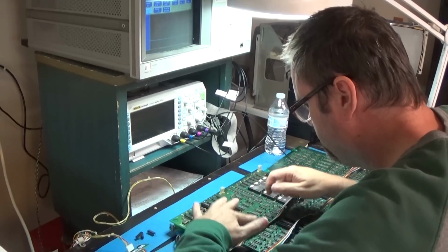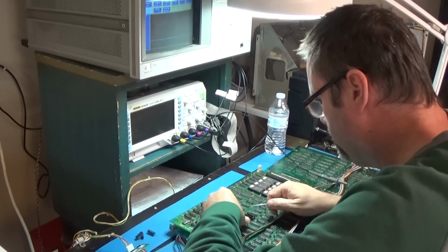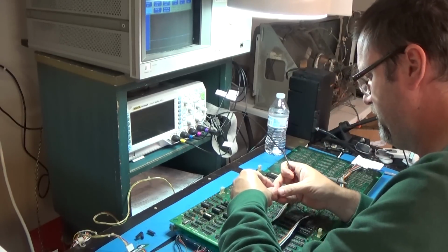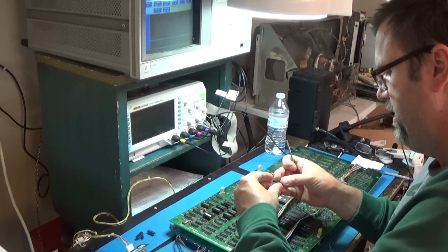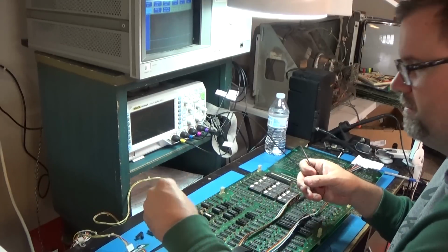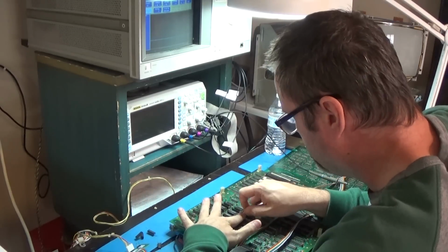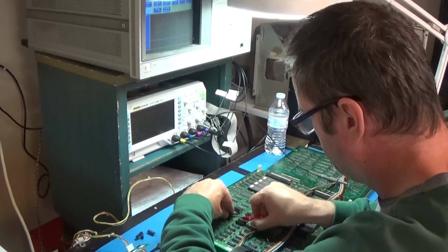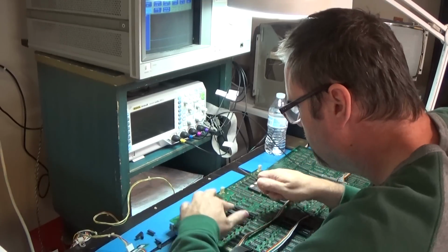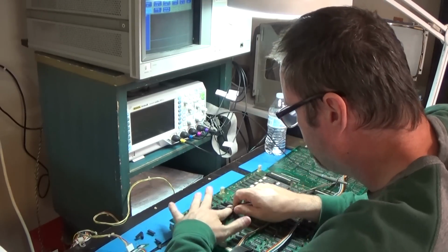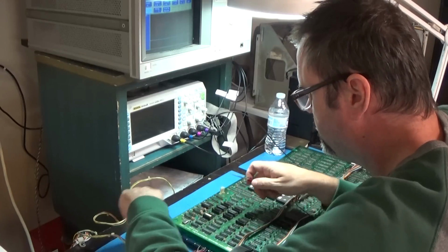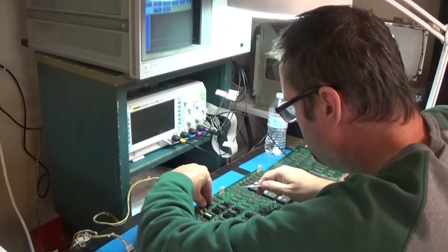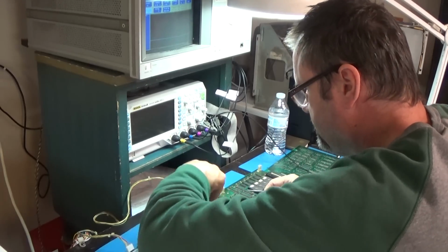These are F series, that's correct. This 163 has soldered legs on it. And it's an S163, it's not even a fast F163. Somebody put S as in Sam series chips, and they have to be F as in Frank.